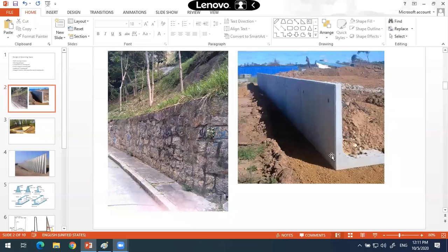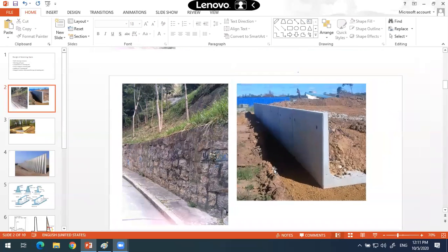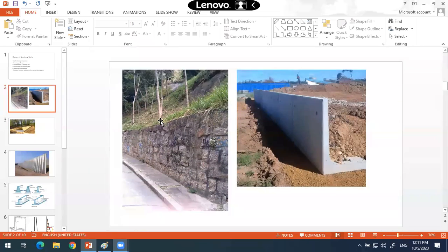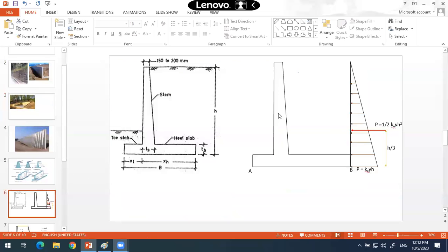If you have problems with slab leakage or any part which will be leaking, in the case of RCC, the first remedy is to remove that water. Provide sufficient drainage provisions. Better than waterproofing is to provide sufficient drainage provisions. Don't allow the water to stand there in a stagnant position. That will create problems. That will corrode your reinforcement. That will deteriorate your concrete. That will pose a lot of problems. So immediately remove that water. That is the best solution. Then if it is not possible, other things are there later.